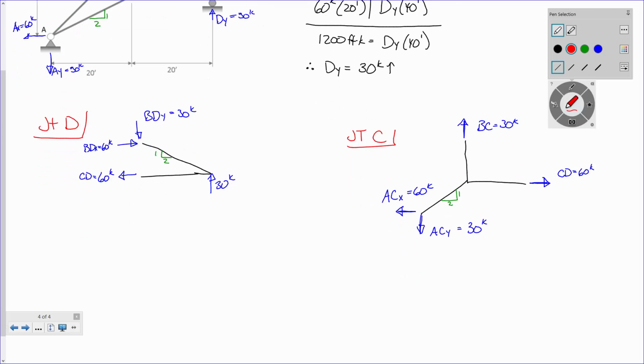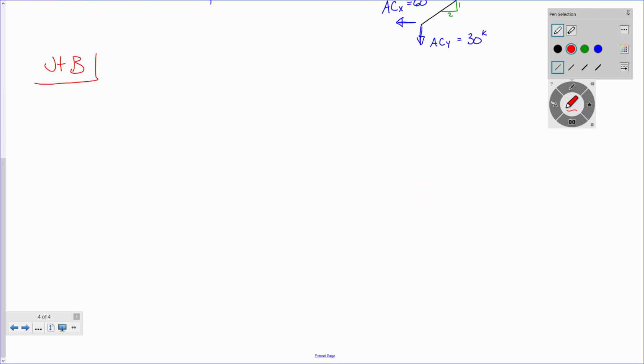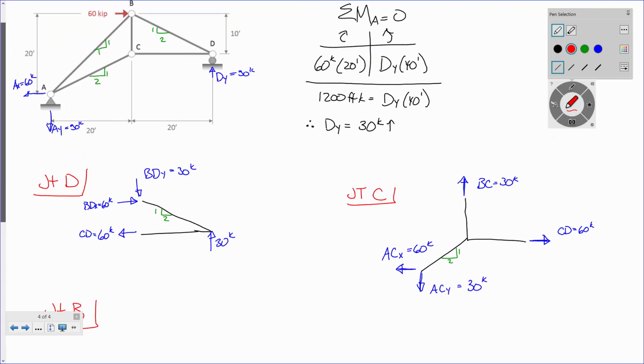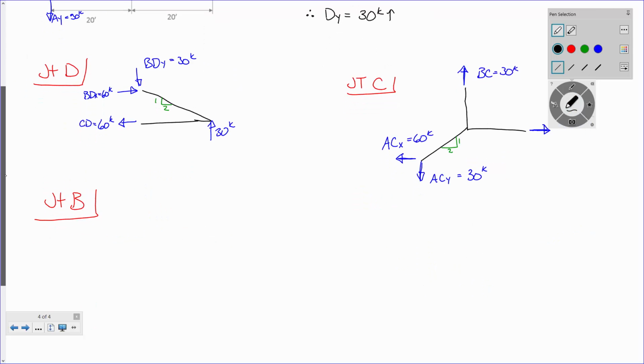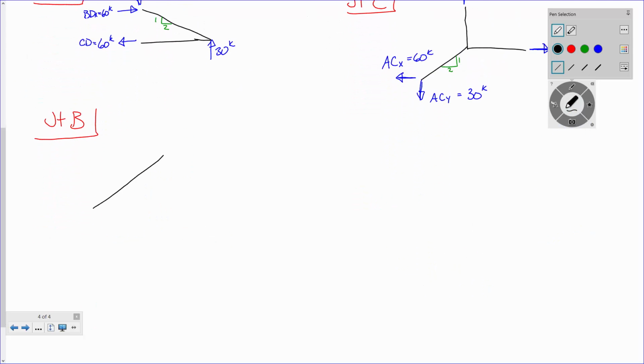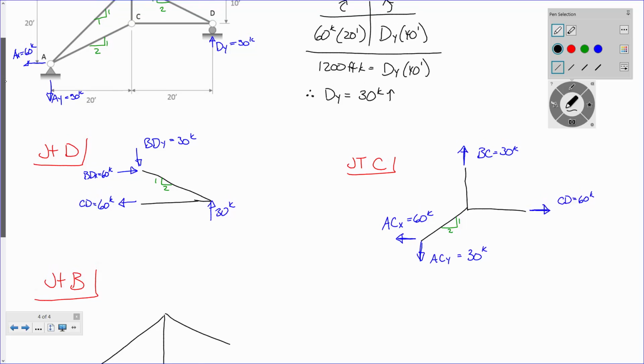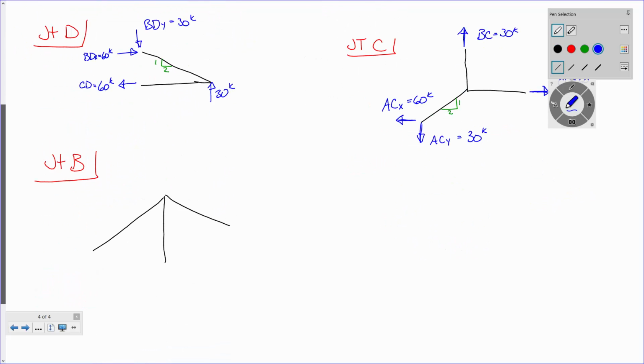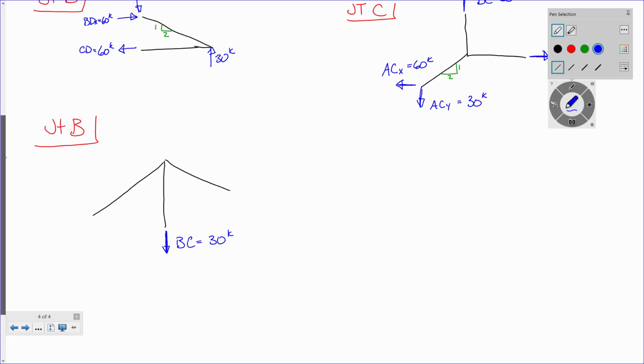All right. So. I know I'm going to need more room, so. Okay. So let's draw the joint. I'm going to scroll up and down a little bit so you all bear with me. So we got that, that, and that. Okay? All right. Now, let's start writing. Do we know this force right here? All right. That's BC, and that's 30 kips acting in what direction? Down.